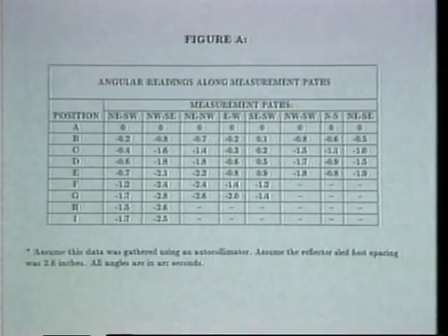In this lab, we have discussed the procedure for mapping plane surfaces. We have seen how individual path measurements can be assembled into the Union Jack pattern to allow area mapping. We have described and demonstrated the electronic level and autocollimator, the 2 instruments most often used in these measurements. The homework assignment for this lab is to process the set of Union Jack data shown in Figure A and construct a plan view map of the area's height variations.